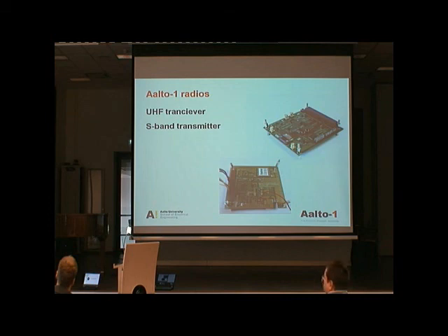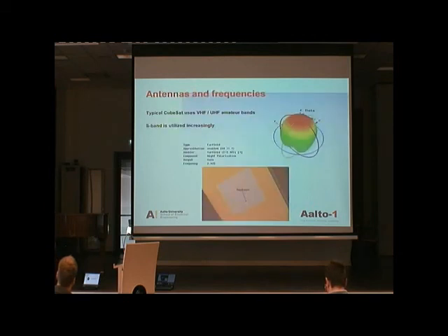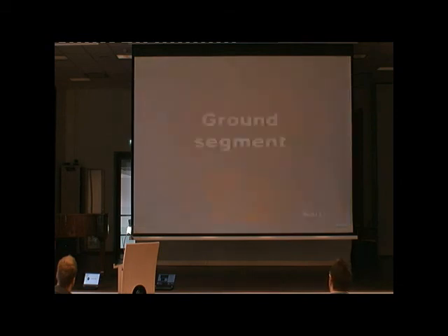Unfortunately, this is way too long to wait for a CubeSat mission, because you want to make your mission in a couple of years. So far, most university missions, and even some commercial, sort of half-commercial missions, are using radio amateur frequencies. Unfortunately, radio amateurs are getting more and more annoyed all the time about these satellites because there are so many. But yes, you build antennas, and you can also use higher frequencies like S-band, for example. There are already CubeSats using S-band in space.